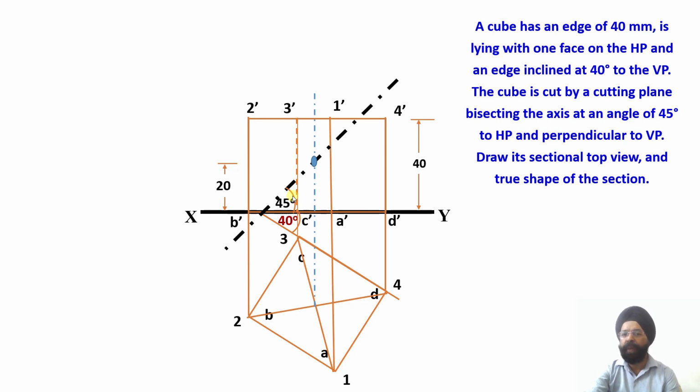Now let us work out the points of intersection. We'll be starting from the base. So you see, this cutting plane has intersected the base of this particular cube, and base means once I draw this vertical line, please check, this is the remainder portion of the solid. So that's why we have darkened it, and this portion of the solid has been discarded. This portion has been cut out and this will be thrown out or this will be discarded. Now let us work out the projections of the points of intersections in the top view.